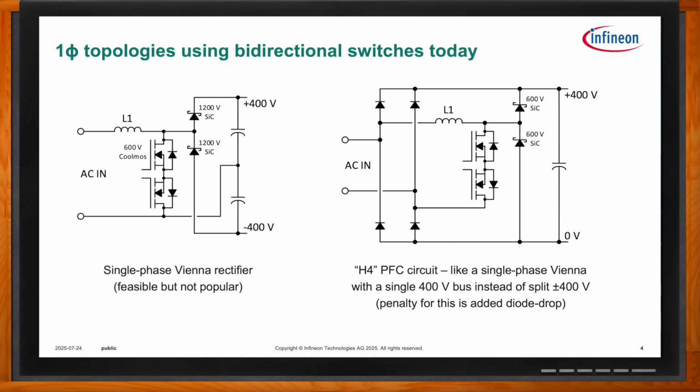It's been shipped in the millions for things like enterprise server power supplies. This is typically used anywhere from 120 volt US, even 100 volt Japan, up to 230, 240 volt single phase at power levels of, let's say, maybe around a kilowatt up to 3 or so kilowatts, in that range of 1 to 3 kW. This has been a popular topology.